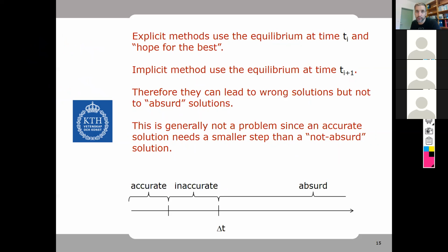And in the case of the implicit numeric method, the assumption that we did is that the acceleration between 2 points is constant, right? Those assumptions are true if the delta t is very small, all right? And the larger it is, the farther from the true they are, and the more wrong our results will be.